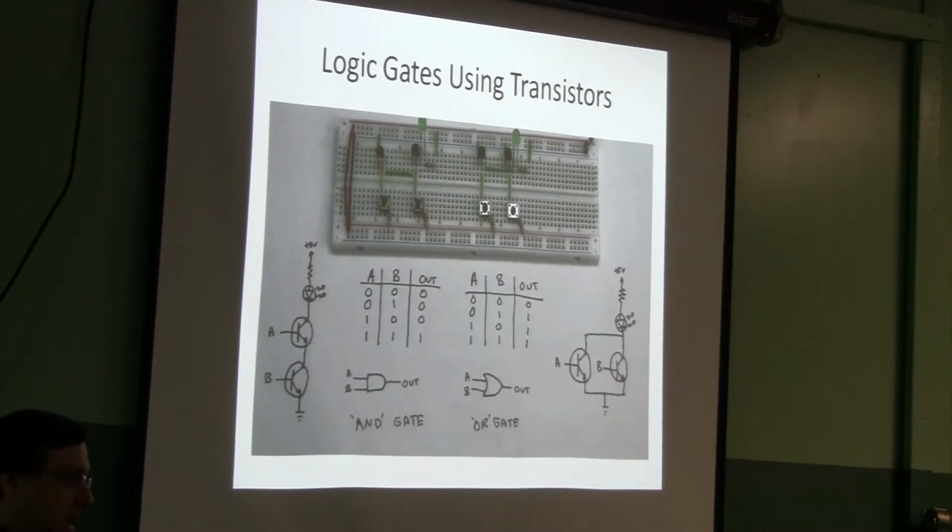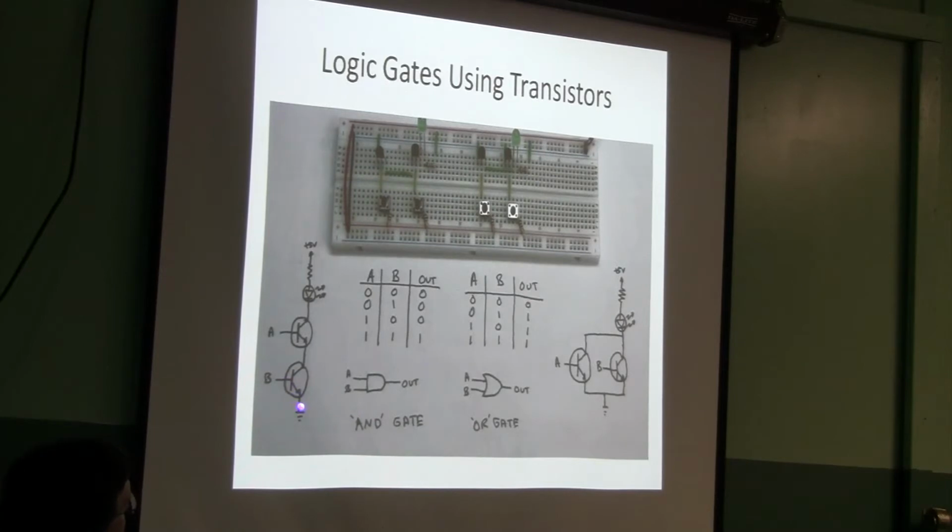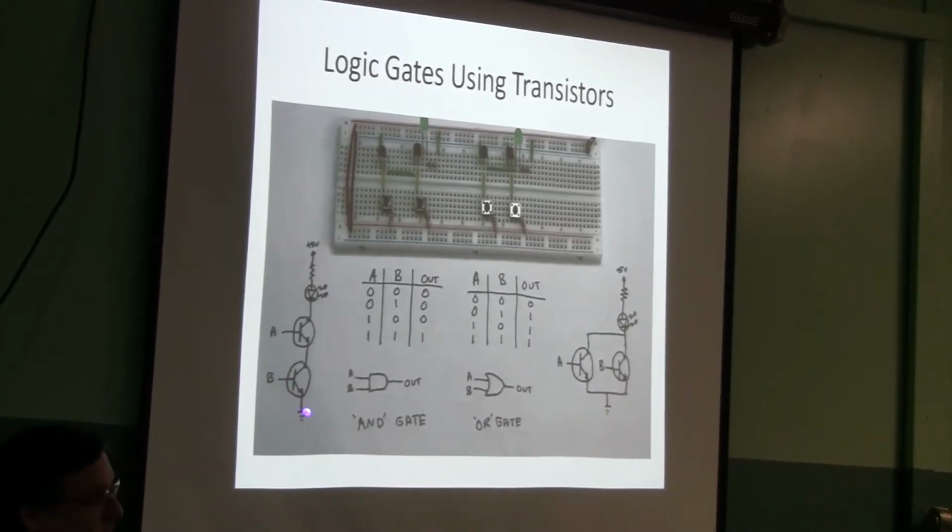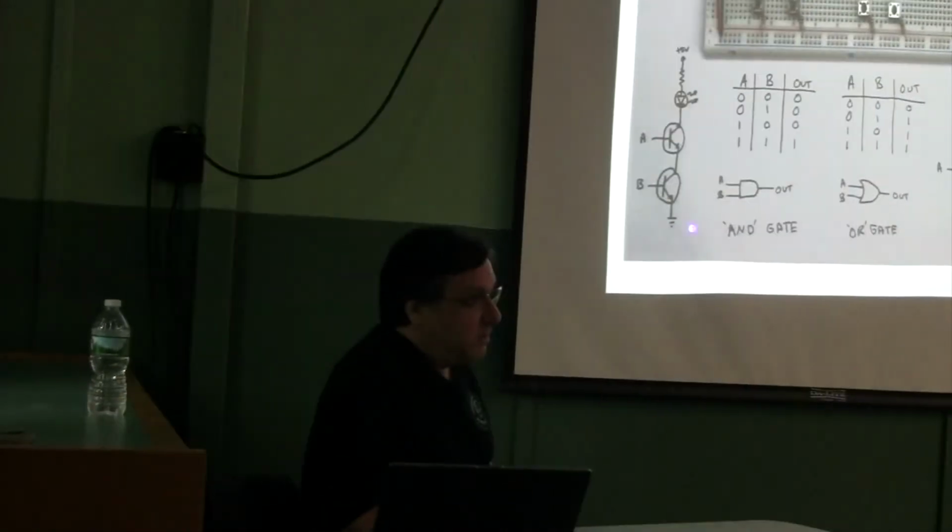You could make a wave. The input wave would be amplified in the output wave. And we want to put a voltage on the input and just have it go all the way on, or take that voltage away and go all the way off. So that's what operating either in cutoff or saturation means. In that case, all you need to do, typically, the base emitter voltage is around 0.6 for a PN junction. And that's beyond the scope of this talk. But basically, if you hit 0.7 volts on the base to ground on the emitter, it's going to turn that transistor on. Okay,